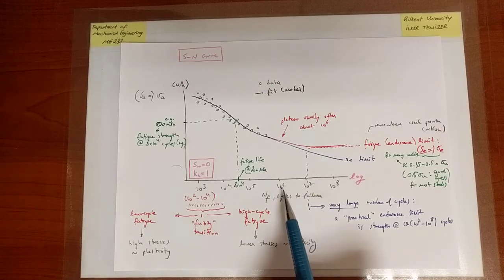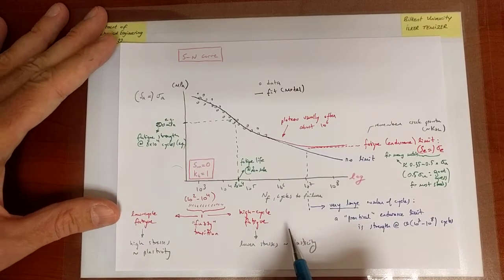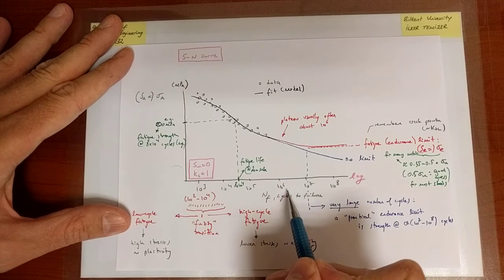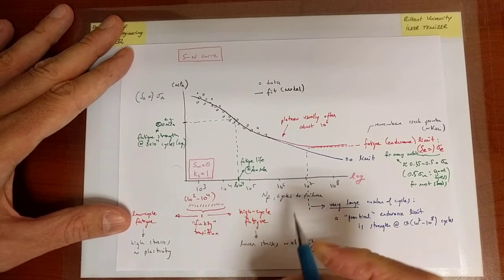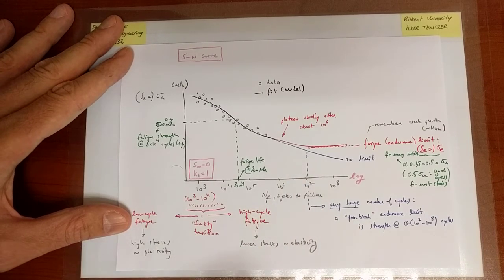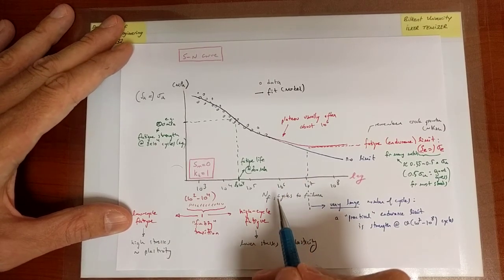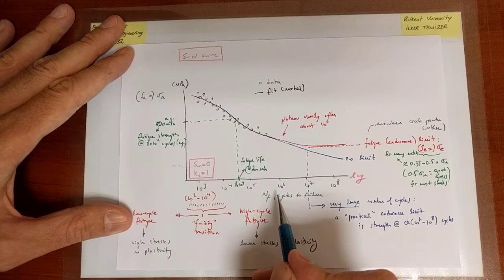Well, it really is, because if you calculate the RPM that your engine runs at, and think about the number of hours it takes to drive, say, from Ankara to Izmir at RPMs certainly beyond 1000, you can easily see that one trip from one city to another is of the order of 10 to the 6, or a million cycles, in the operating life of the engine. So 10 to the 6 is not actually a very large number for some cases.